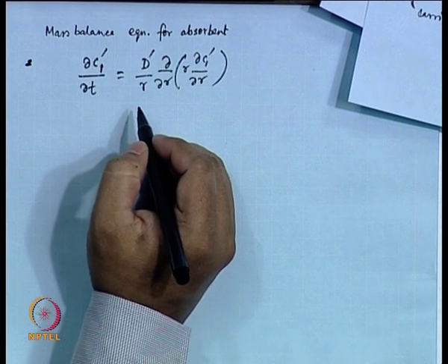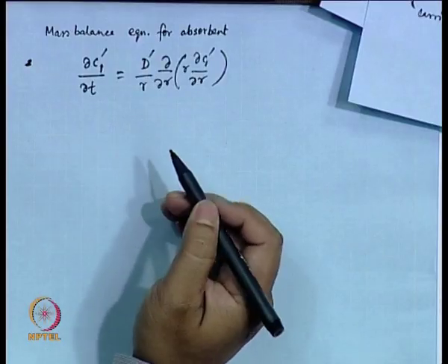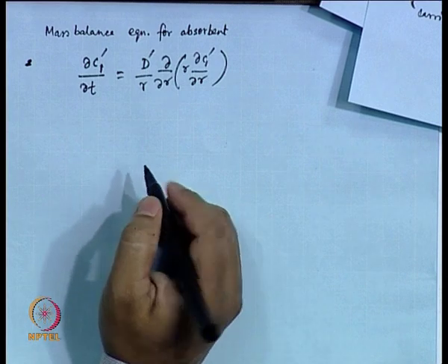You can probably get a quick feel of this. This diffusivity would typically be the bulk diffusivity, that means the diffusivity in a gas phase, multiplied by the tortuosity factor. You have a porous network of this adsorbent that has a tortuosity factor that you have to multiply. So, it will definitely be an order of magnitude or more different. That is why you call it D prime. So, there would be only radial diffusion; axial diffusion, you know that concentration gradient is not important. So, that part is gone. So, this is the only mass balance equation that you have for the adsorbent phase.